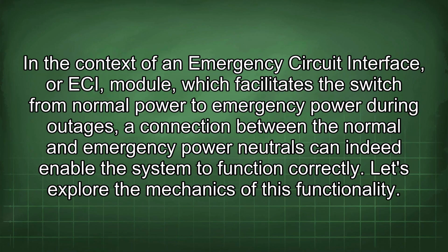In the context of an emergency circuit interface, or ECI module, which facilitates the switch from normal power to emergency power during outages, a connection between the normal and emergency power neutrals can indeed enable the system to function correctly. Let's explore the mechanics of this functionality.